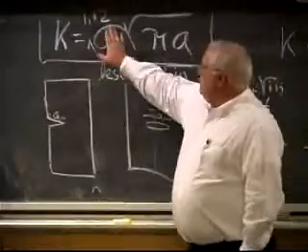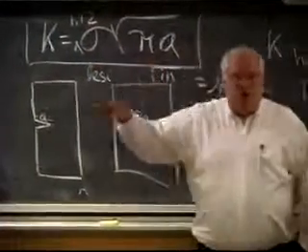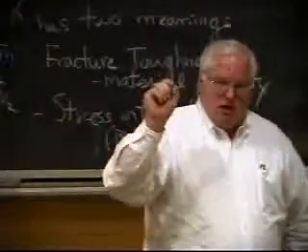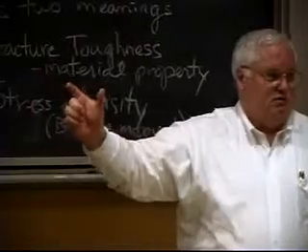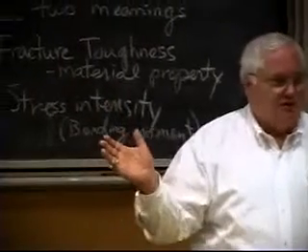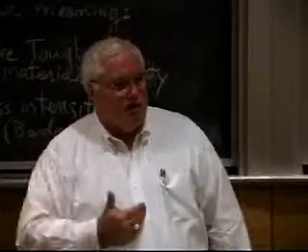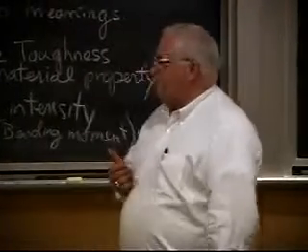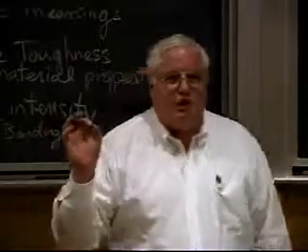99.5% of the time, you don't need the 1.12, you don't need the Q, you want to know what ballpark you're in. I want to know, is my critical flaw size 3/1000 of an inch, or is it 3 inches? It makes a difference, okay, in terms of what I have to inspect for in the structure that I'm going to fabricate. It turns out that for typical fracture toughnesses of ceramics, you can put in anything you want, but